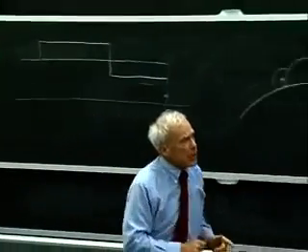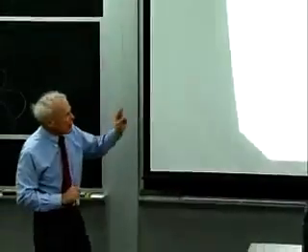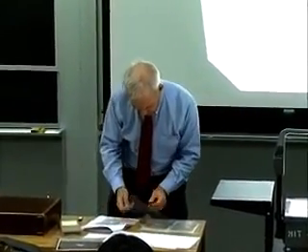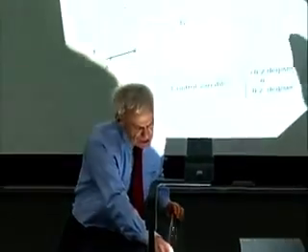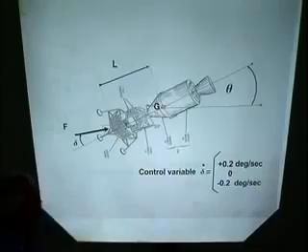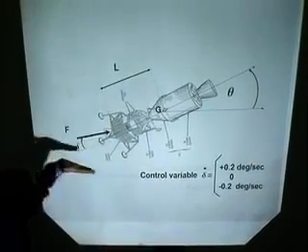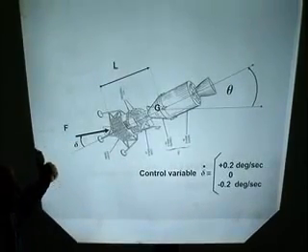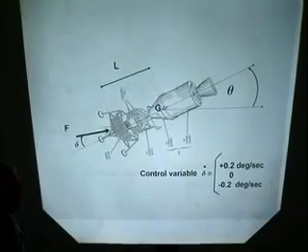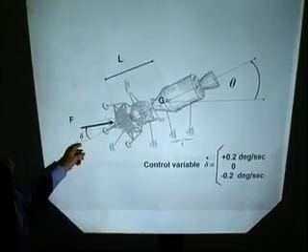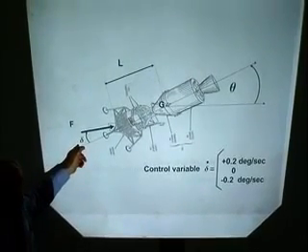Well, I said, let's find the minimum time controller to control any initial condition in this configuration. But this was a third-order plant. The control variable in this case is not angular acceleration. Now we're doing rotational control. We're trying to control the deviation in angle from the direction we want to thrust, and the angular velocity around that pitch axis. But the control variable isn't instantaneously applied torque. The control variable is the rate of change of the gimbal angle.